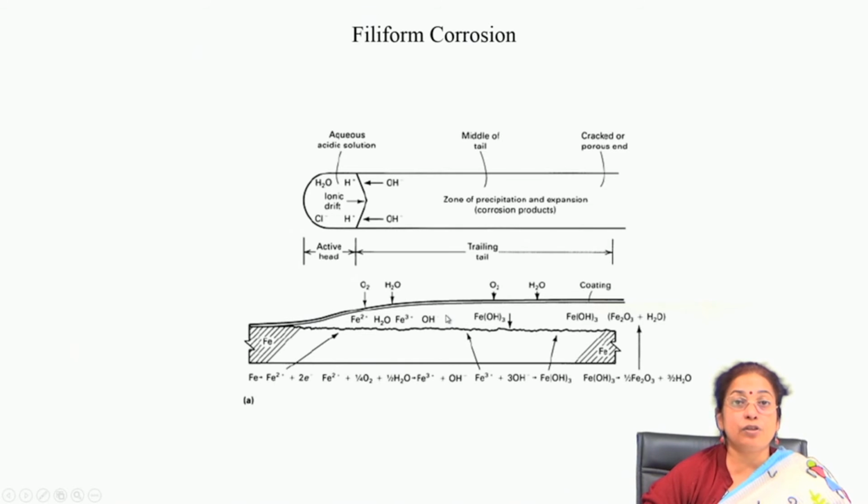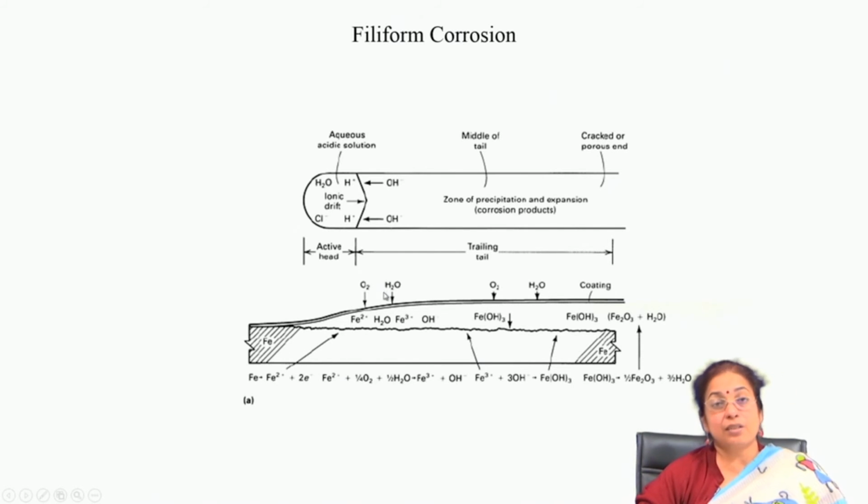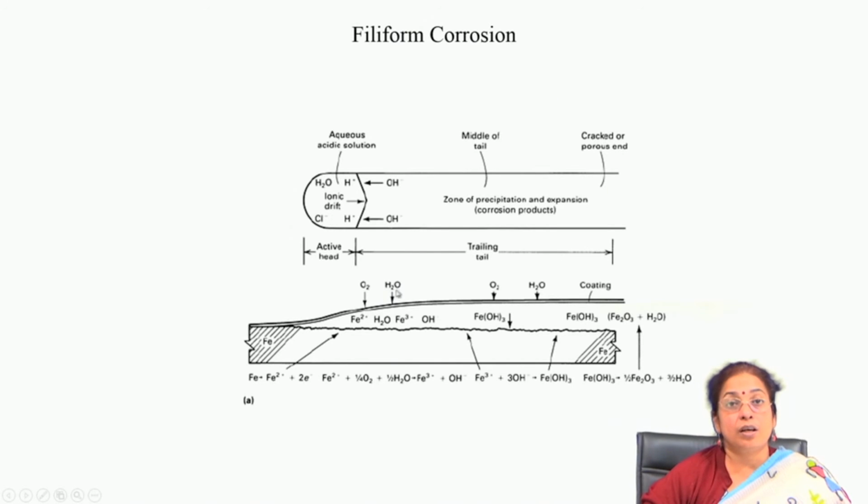If you look at the formation rate in different regions, you will find that it is higher in some regions and not uniform, because wherever there is a very small porosity, the water molecules migrate through that porous region and iron hydroxide forms. Whenever there is hydroxide formation, there will be much more moisture absorption.